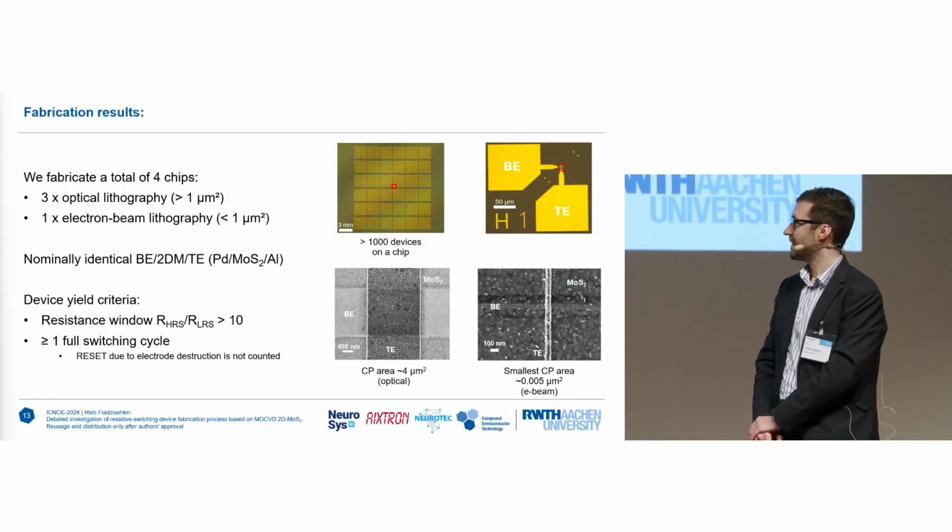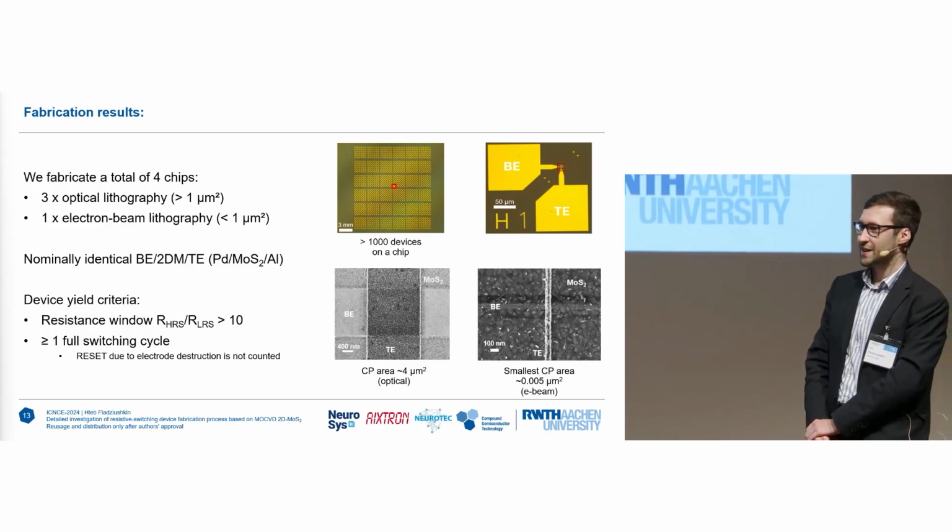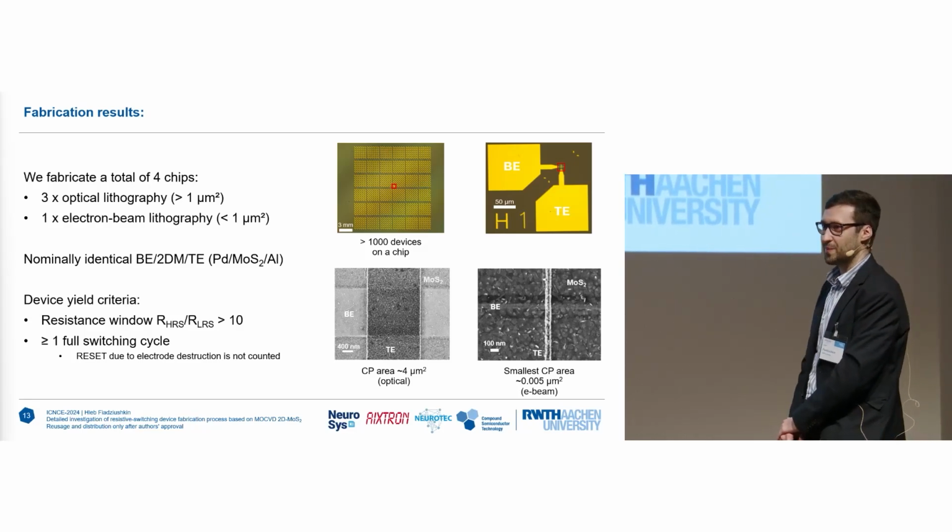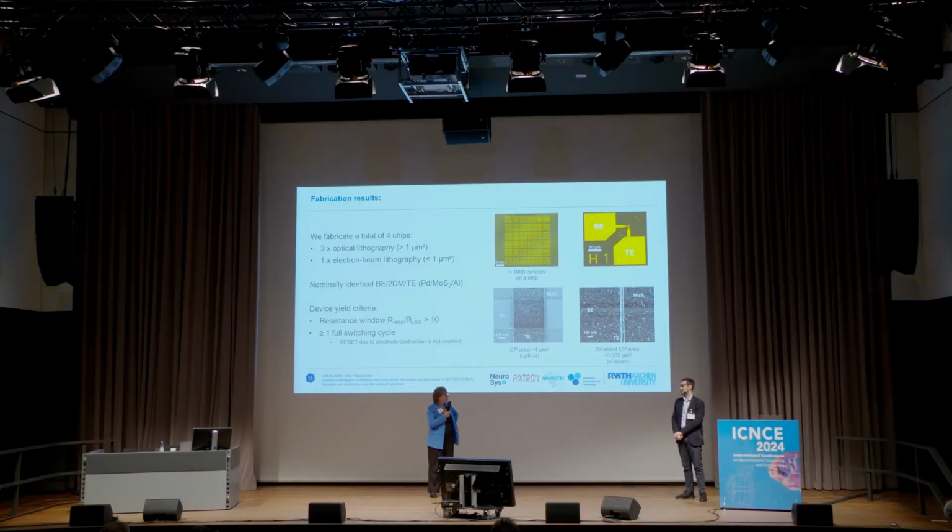Okay, and what do you think is the switching mechanism? That's actually still a very open discussion. The field, I think, solely converges on the idea that it's a filamentary switching type. This is clear from the two-dimensional curves, but what makes the filament? Actually, I think in this case that would be aluminum atoms, because it's more mobile than palladium. And from some electrical data, we see some hints that we also have filamentary switching type in these devices. Okay. Yeah.